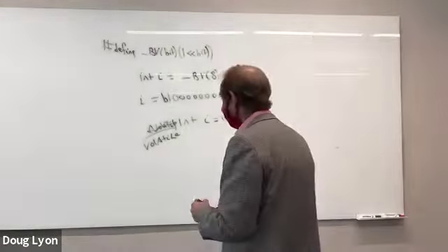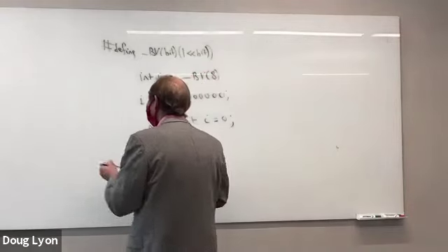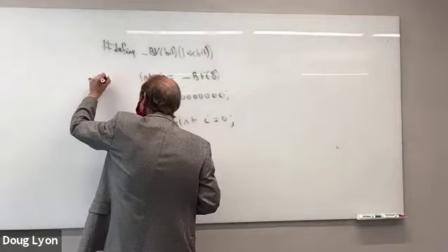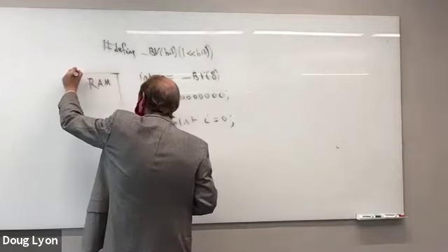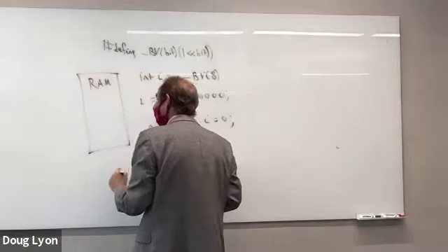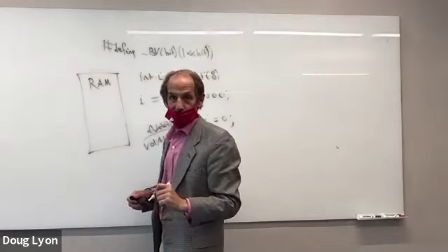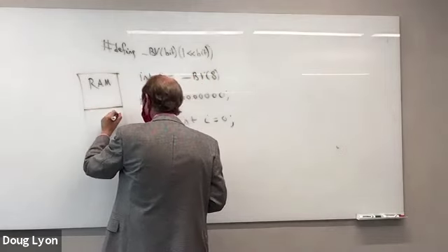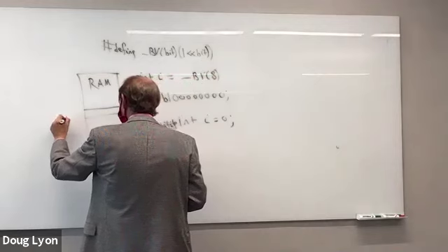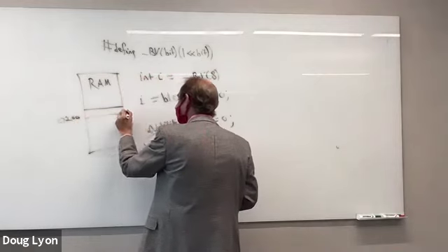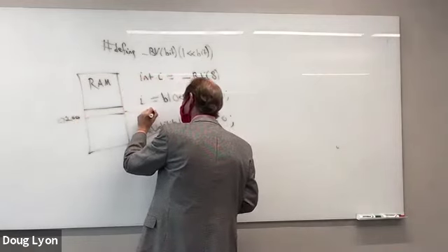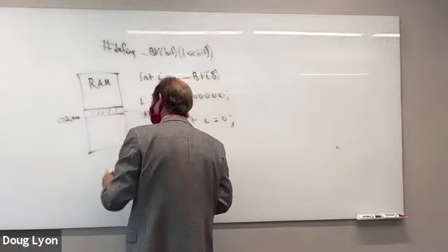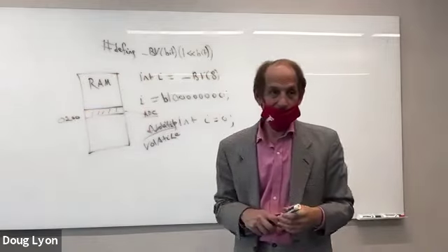A lot of times what will happen is RAM has devices that reside at a specific address. And what will happen at that address, let's say it's 0200, is the ADC converter can write to that location some value for the CPU to look at later.